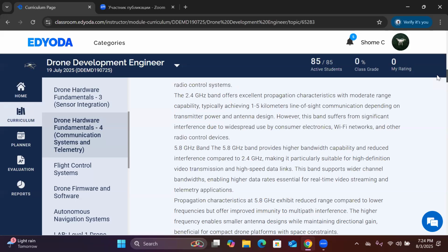That RF power amplifier will be able to amplify the power level. Say we are transmitting from the wireless LAN module a power level of 30 dBm, right? So 30 dBm corresponds to 1 watt. So for 1 watt, we are getting a range of 5 kilometer.